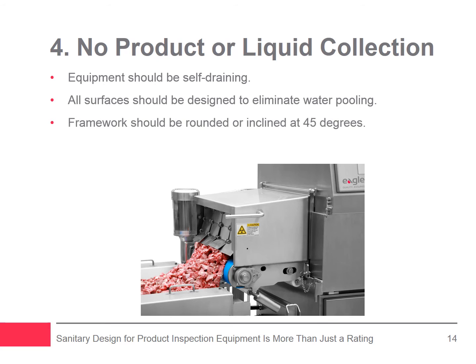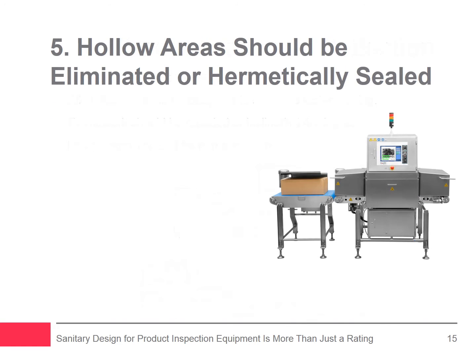The framework should be rounded or inclined at 45 degrees, and flat under surfaces that are difficult to see or clean should be avoided. Belt tension should be adequate throughout operations to prevent water pooling on belts, and the materials used should be non-absorbent.